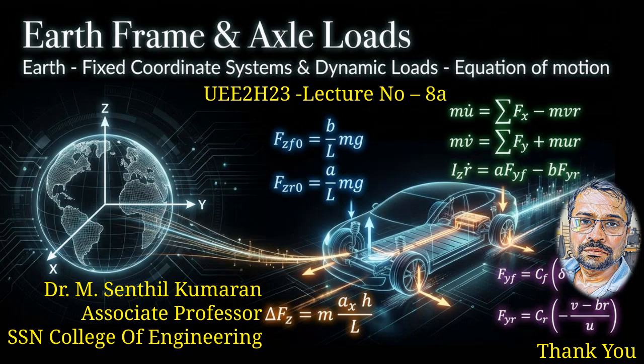In summary, today we established the foundation for vehicle motion analysis. We defined the earth-fixed frame, explained its relationship to vehicle-fixed velocity components, derived dynamic axle loads, and developed full equations of motion, including yaw dynamics. With these tools, engineers simulate braking stability, cornering limits, rollover risks, and control strategies for ABS, ESC, and autonomous vehicles. In our next session, we will apply these equations to a real-time vehicle problem.